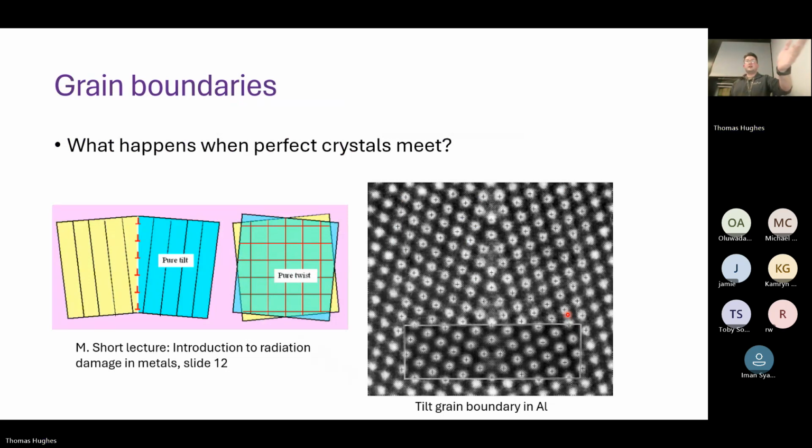So you have essentially lots of, you can see this grain boundary down the middle. You see the atoms are sort of in a triangle shape going together, and there's like a bit in the middle where they meet. There's some missing atoms there. And this is essentially, as a defect, almost a 1D defect. If you stack lots of dislocations together, you get a 2D line, which is our grain boundary.